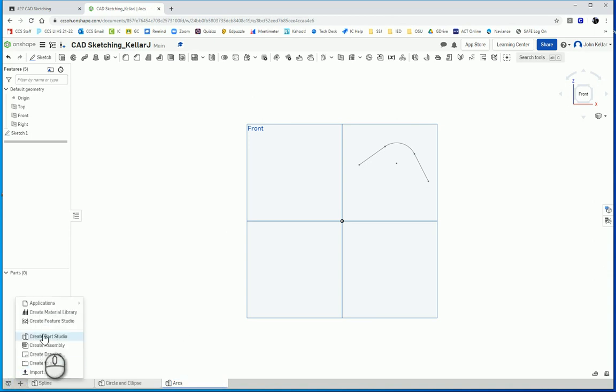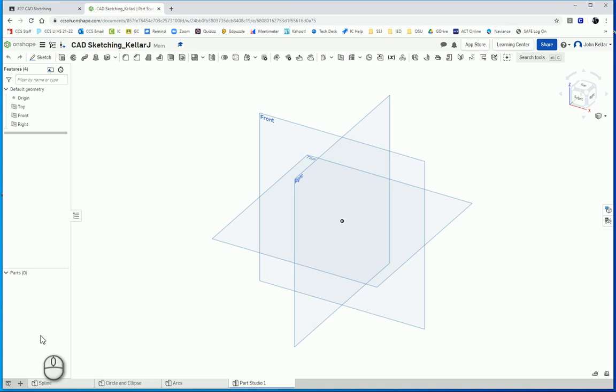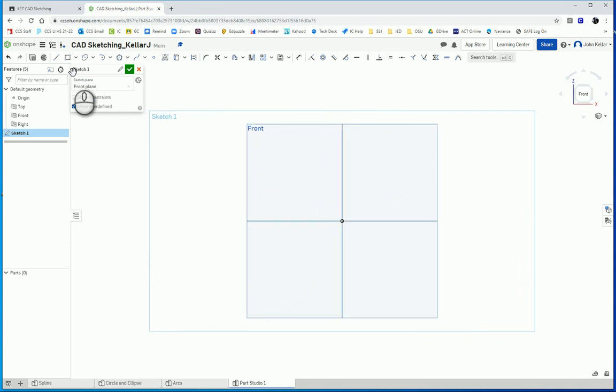And new part studio. The next one is a fillet. Okay. Now there's a before and after picture. You only have to turn the before into the after. Okay, you don't have to have both images on there. So I'm going to start there. And this should be a 2 by 1.5. So there, that width should be 2 and the height should be 1.5.